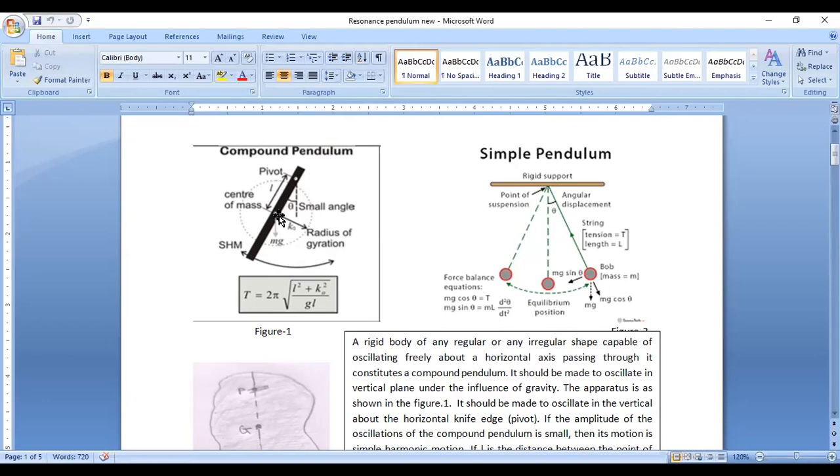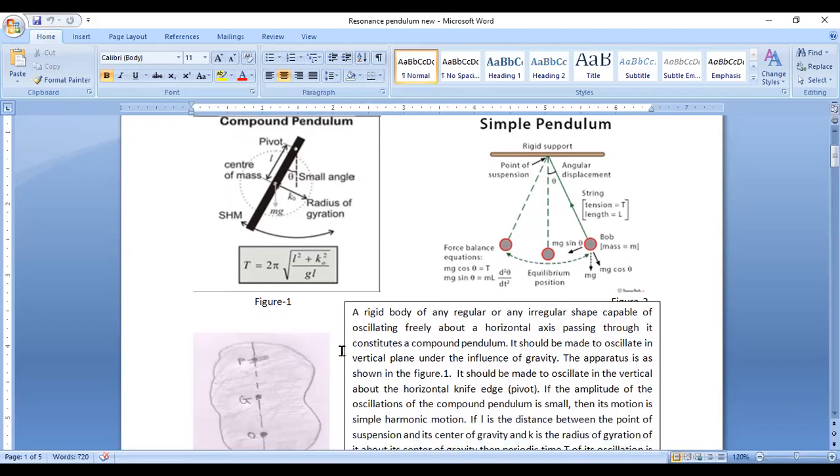If you consider the point P, and suspend your pendulum with respect to P, and find the periodic time of the pendulum, then you will get the distance between the point P and G equal to L1. But since there are two possible values, L1 and L2, there must be another point of suspension on the axis on the other side of the center of gravity.